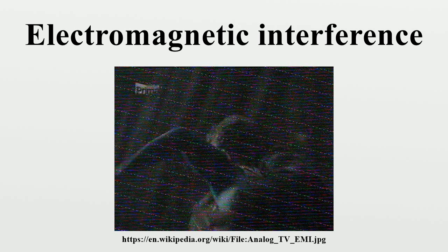Techniques to deal with RFI range from filters in hardware to advanced algorithms in software. One way to deal with strong transmitters is to filter out the frequency of the source completely. This is, for example, the case for the LOFAR observatory, which filters out the FM radio stations between 90 to 110 MHz. It is important to remove such strong sources of interference as soon as possible, because they might saturate the highly sensitive receivers, which means that the received signal is stronger than the receiver can handle. However, filtering out a frequency band implies that these frequencies can never be observed with the instrument.